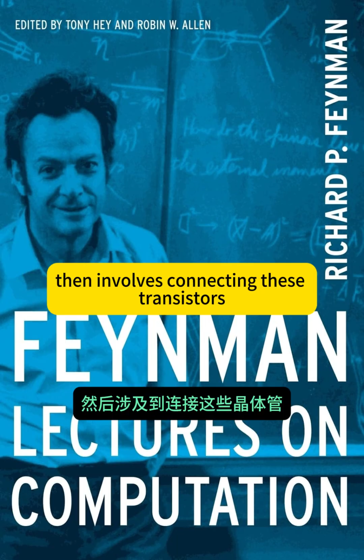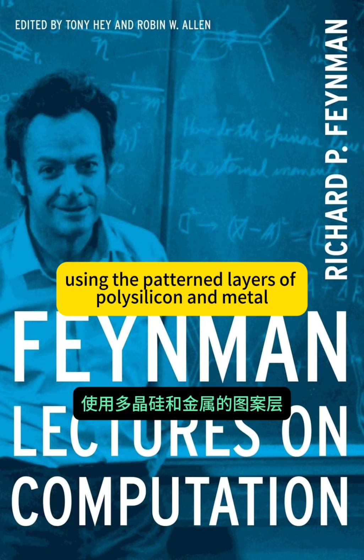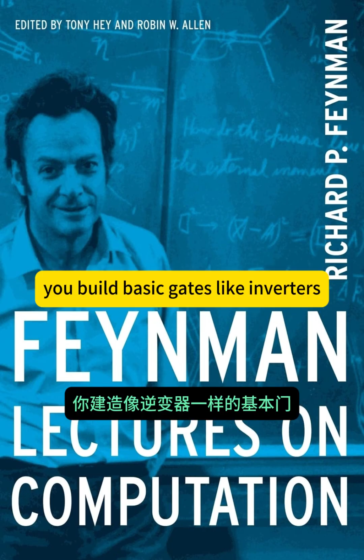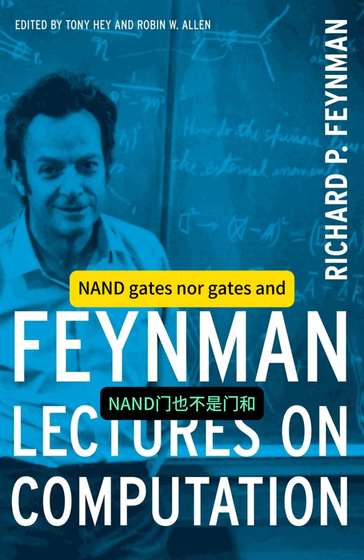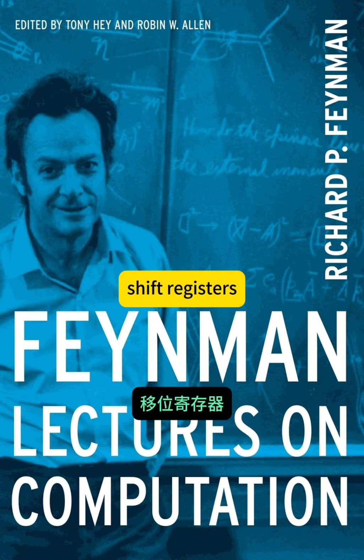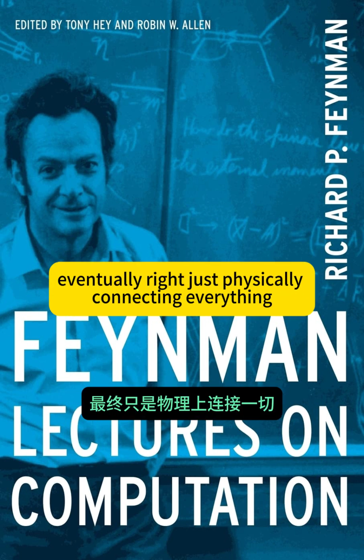Building circuits then involves connecting these transistors. Yes, using the patterned layers of polysilicon and metal, with connections made through vias or contacts between layers. You build basic gates like inverters, NAND gates, NOR gates, and wire them together to make flip-flops, adders, shift registers, eventually the whole processor. Wiring itself must become a problem eventually, right? Just physically connecting everything. Absolutely.